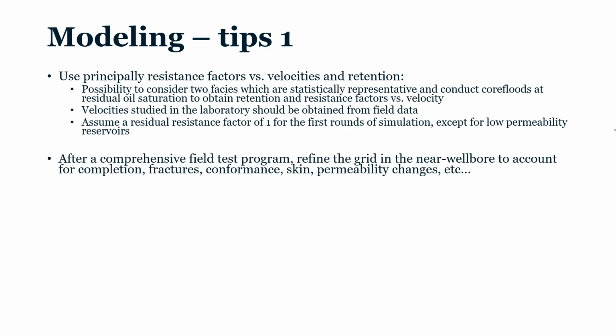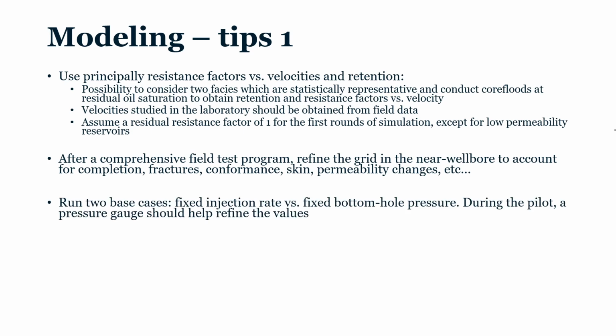So after a field test program, you need to refine the grid and understand the near wellbore. If you can, before running the simulation, run an injectivity test to get the values and compare with simulation. So that's going to be very, very important. You need to run two cases. Very often people start with a bottom hole pressure constraint because they are afraid of fracturing, even though very often they already have induced fractures.